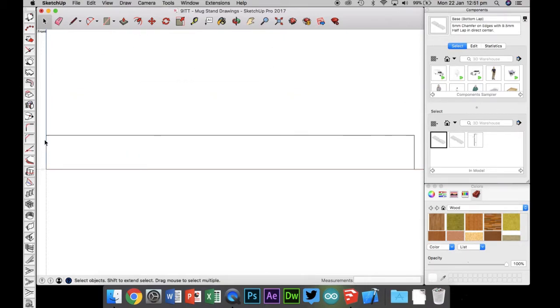Looking at the side of the timber, we've got 19 millimeters of height along the blue axis, and we've got 200 millimeters of length. What we need to do is we need to start by finding the center, because in the exact center of this piece of timber, we're going to need to cut out a bit of a rebate halving joint, what we call a cross halving joint, and it's very similar to a rebate.